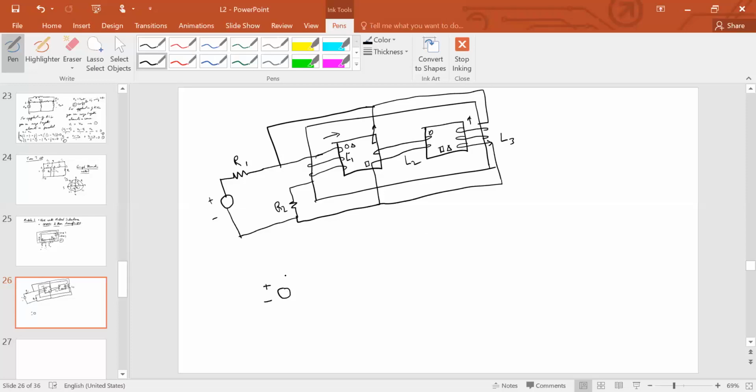All right. So now if you want to draw this circuit with these polarities marked, this is what the circuit will look like. R1. So this was the goal basically. I've just shown you how to mark out the polarities, but at the end of the day, once you have marked out the polarities, you want to forget about this magnetic circuit and we want to deal exclusively with the electrical circuit. So now you have these polarities marked here, and this R2. All right. This is V in.